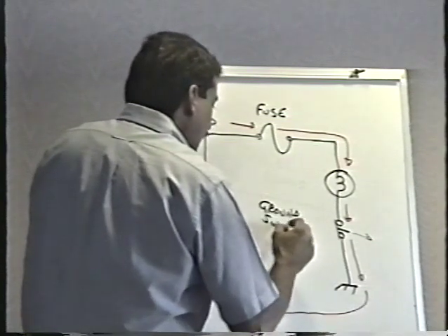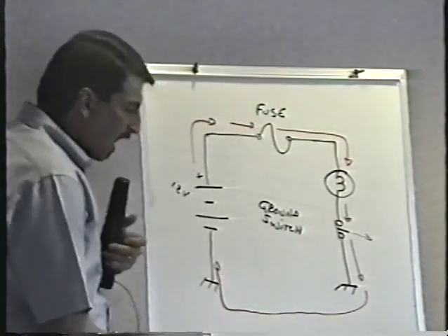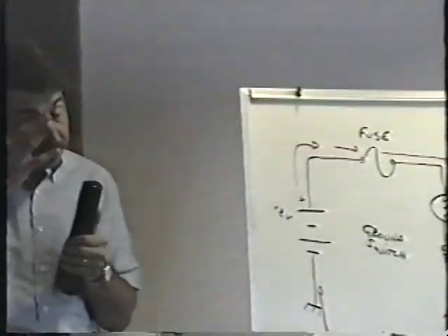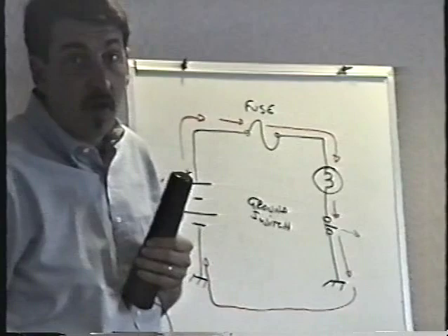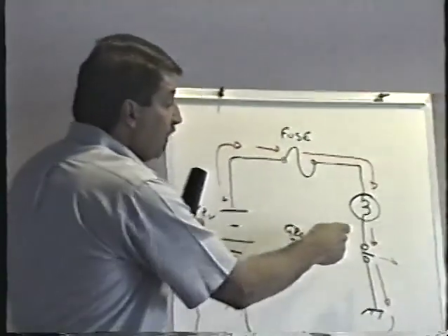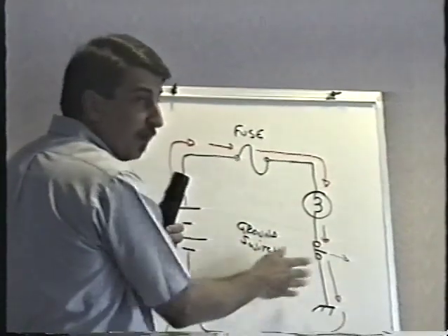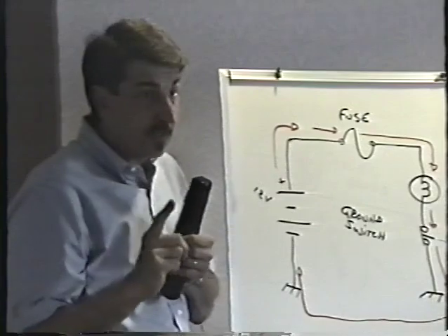It's called a ground switch. And this is actually the most common way to control things in electronics. When we're dealing with electronic controls, like turning light bulbs on and off, we very often use a ground switch. Instead of switching the source in and out, we simply switch the ground in and out. Pinball machines are the same way. We'll see this on Saturday.